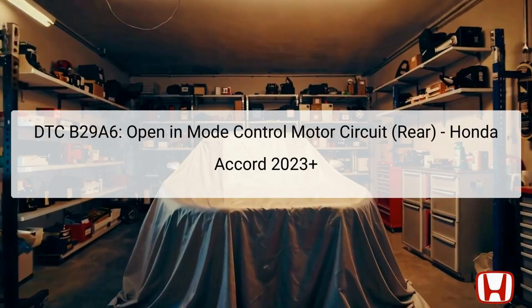The fault code DTC B29A6 indicates an issue specifically related to the mode control motor circuit located in the rear section of a 2023 Honda Accord. This error signifies that an open circuit has been detected, leading to a malfunction in the rear mode control motor.